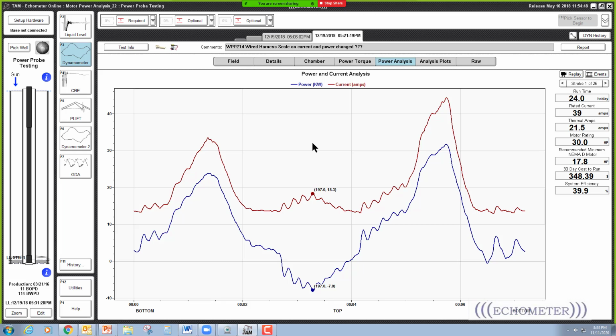My point here is that if you use a power probe, you may want to go to your wells and try hooking up the power probe wrong and collecting data, to see how your normal well power looks when the amp sensor clamps and the voltage connector clamps aren't connected properly to the panel, because it typically impacts the kW plot.